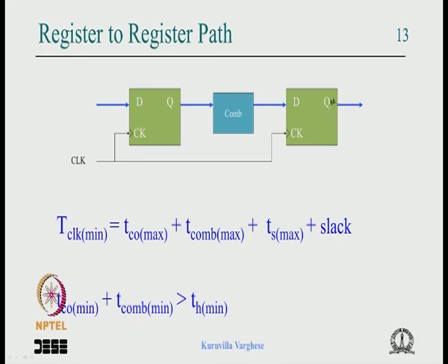Similarly, you have a data path giving the signal to the state machine, and maybe the state machine receives output in response to a positive edge triggered clock register and a negative edge triggered register. So there is a big issue. So you have to stick to one polarity, it can be clock or clock bar.